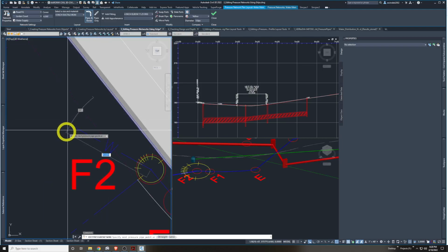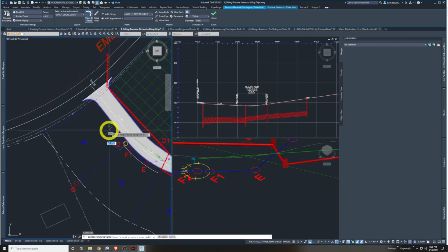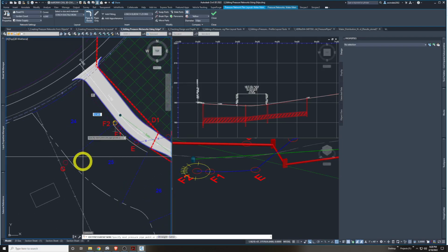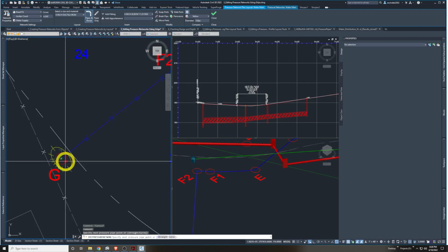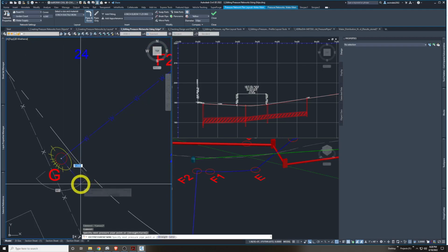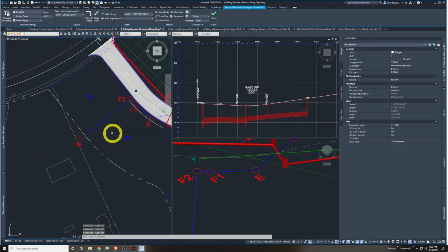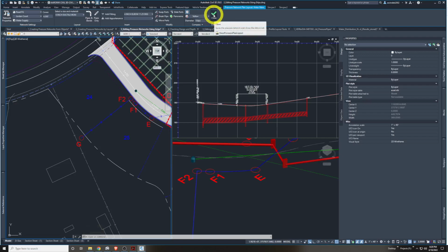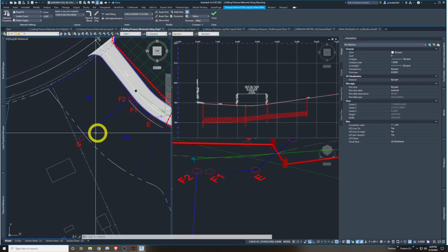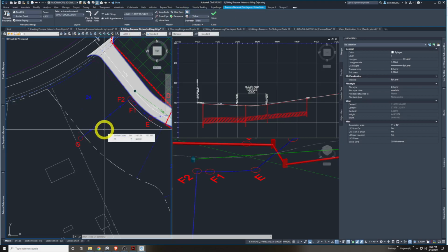We have our compass that gives us the proper deflection angles, right? We're going to move up to G, which is over here. Let's click the center of G. Okay, we went that way. Let's hit escape to clear all selections and get off of our pressure pipe network tools. They're still open. You have to physically close them in this newer version with this button here. And this is different edits to your compass saying what it can do in different directions, what kind of deflections and colors.